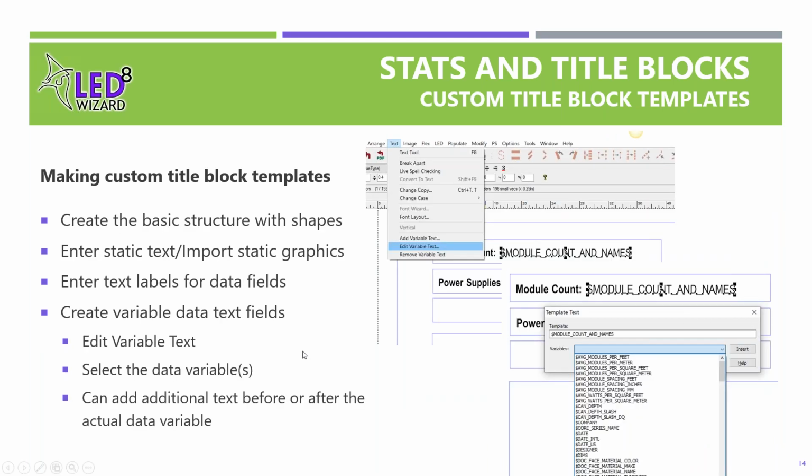So, first thing I would do in the title block, create the basic structure with some shapes, put in some static text, import some static graphics. Again, if you're starting from scratch, we'll create some text labels, right? So here, power supplies, module count, basic labels, and then we'll create the variable data text fields. These are the text fields like here, $sign module count and names.